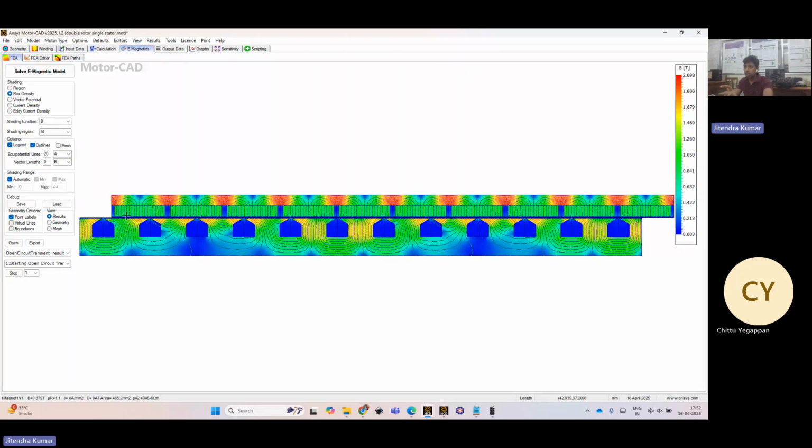This magnet flux was crossing directly to the rotor core. But here now they have to travel in the back iron of a stator. Though there is only one stator and only one rotor, this back iron path is not very effective. If you could make flux transit directly from one point to another without crossing the back iron, then you are reducing the material. So that is why the earlier version is called a yokeless machine, yokeless stator.